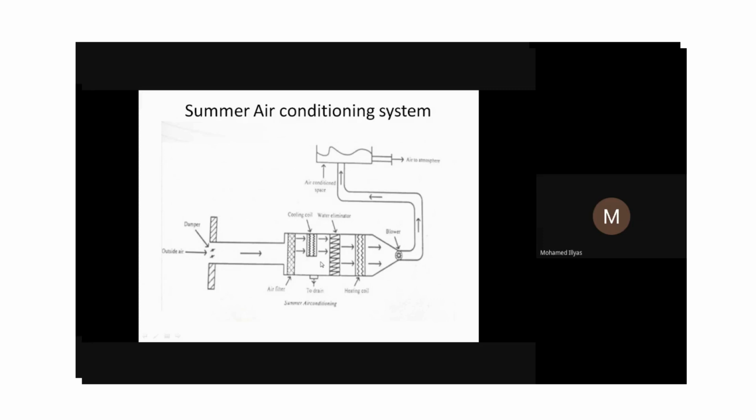When we represent the same process in the temperature-entropy diagram, 1 to 2 is the compression process, which we call isentropic compression taking place in the compressor. The refrigerant will first be in the superheated state, and after that it will come to the dry saturated state. We observe our pressure and enthalpy at one point on the TS diagram here. So starting from point 1 to point 2, as the temperature is increasing, the pressure is increasing.